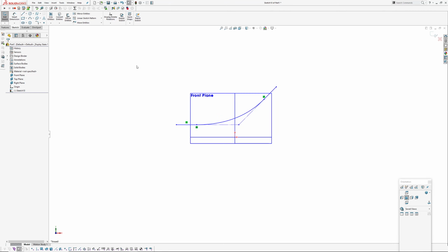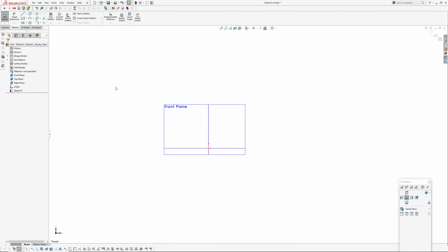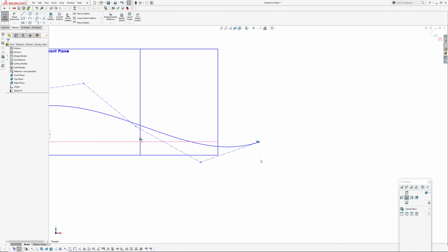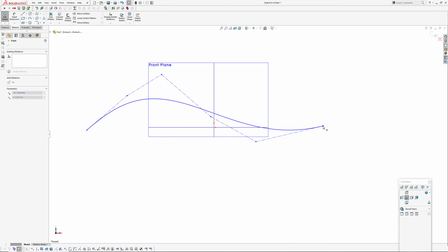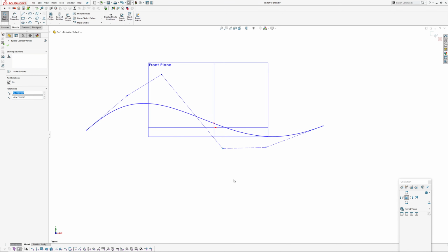Okay, so if you want to create a spline that's curvature continuous, with constraints at each end, the minimum degree is a degree 5 because you need 4, 5, 6 points. If you want each end to be independent from the other, then there's our first point, positional, second point for tangent, and you need the third point, which is the curvature continuous point. So same on this end, 1, 2, 3, and you can see curve degree 5.